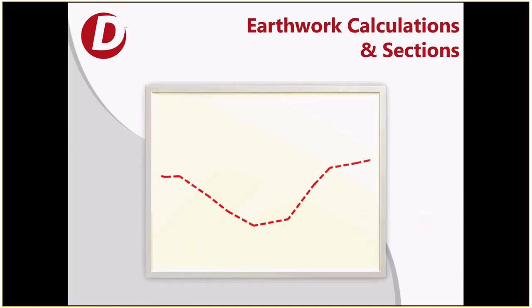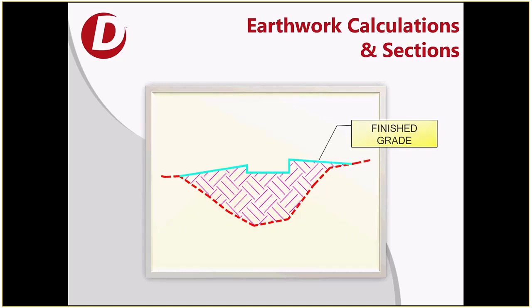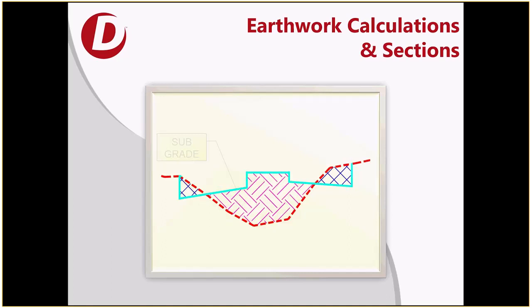So we're going to start with a very simplistic model of how we generate earthwork volumes. And this is going too fast, Joe. This is cross-section view, but keep in mind we're really talking about generating a 3-dimensional model in Civil 3D. The cross-section view is just to simplify the principles. So the red line, of course, is the survey section. The magenta or cyan line is the subgrade, or the finished grade of the earthwork, if you will.